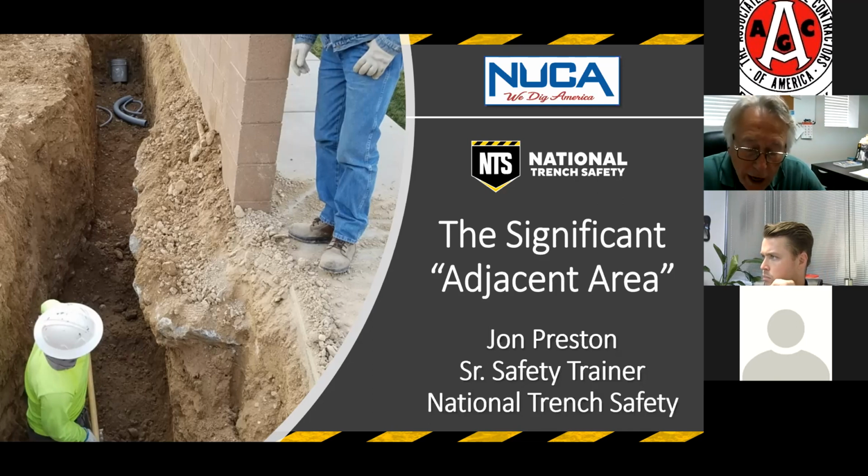So that is why we want to make sure that the gap between the face of the trench and the side of the trench box is minimized, so that the shield does not move sideways when the soil caves in and hits it. So that's a very important concept. I want to make sure everybody understands that we need to make sure the shield does not move laterally.